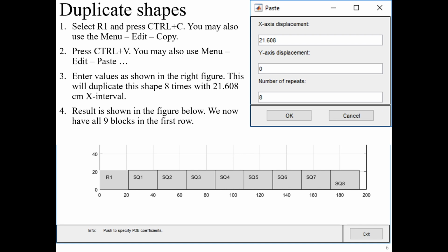You need to review this dialog to make sure that everything is correct. When you click OK, those 8 assemblies will be generated for you. There's no undo, so if you make a mistake, you will have to delete those created assemblies and do it again.